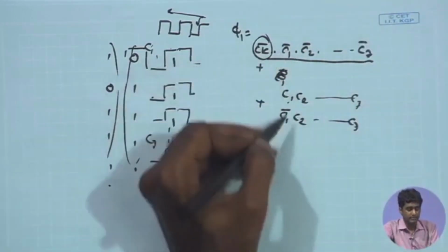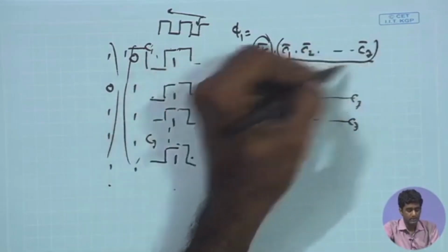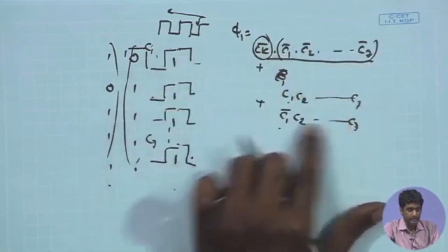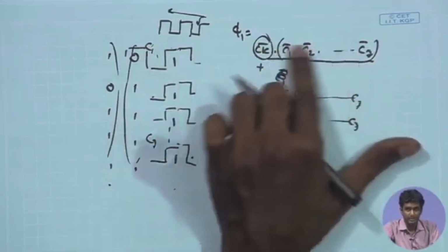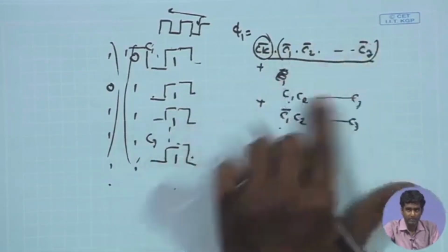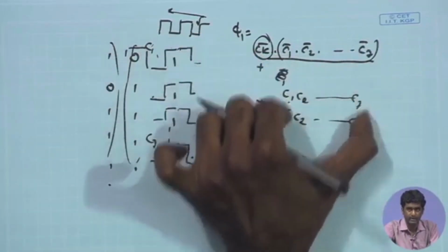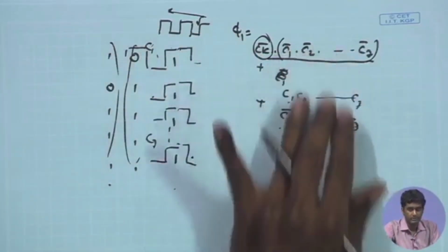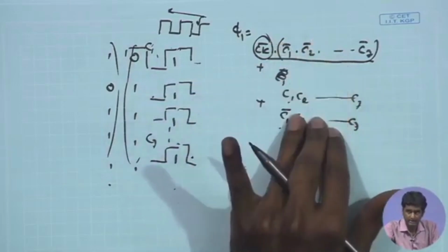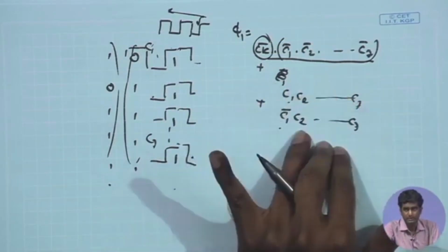So, you have basically the AND gates taking care of these min terms, they are called min terms, combination of these AND functions, and then they are ORed together. So, basically a bunch of AND gates followed by OR gates. Now, there is a question regarding implementation of these AND gates and OR gates at transistor level. How do we implement this?